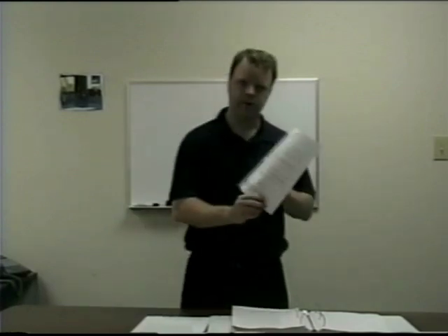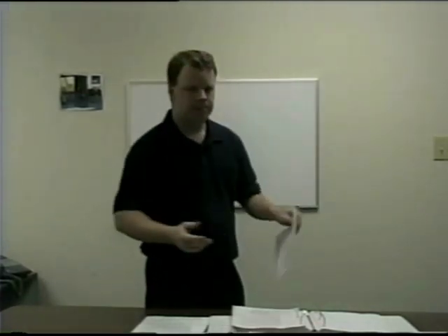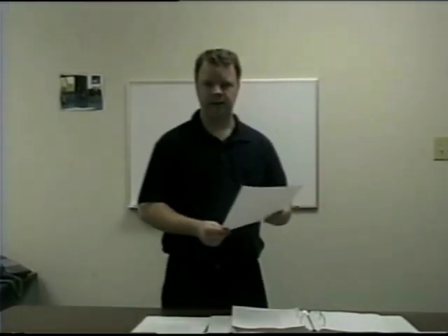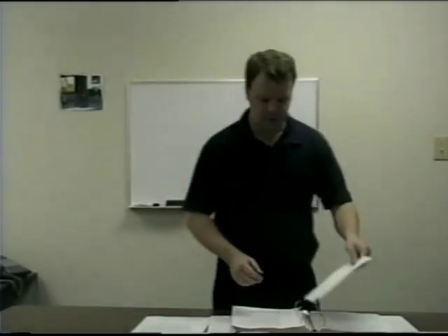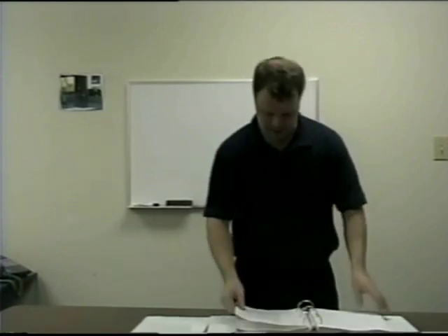Now let's take a look at here. Verify soil information report is on job and reviewed. Note elevation of water table. Things like this. Do you know where your soils report is? There's a testing agency that did that. Oftentimes it's in the spec book, but things like that. This is for site work. These are very easily put together. They're put together by the section number.